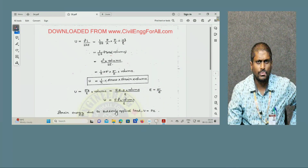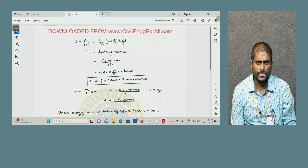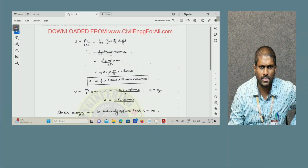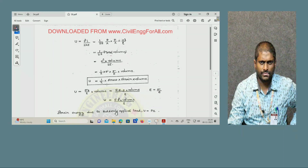Then U equals P square L by 2 AE, which can be written as 1 by 2 A into P by A into P by A into AL. Therefore it is half into sigma into delta, sigma square into volume by E. Therefore half into sigma by E into volume. Then U equals half into stress into strain into volume, U equals sigma epsilon by 2 into volume, equals Young's modulus into epsilon into volume divided by 2.